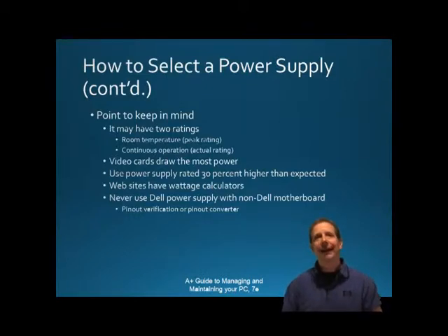Point 5. The Dell ATX power supplies and motherboards might not use the standard P1 pinouts for ATX, although the power connectors look the same. For this reason, never use a Dell power supply with a non-Dell motherboard, or a Dell motherboard with a non-Dell power supply, without first verifying the power connector pinouts match. Otherwise, you might destroy the power supply, the motherboard, or both.